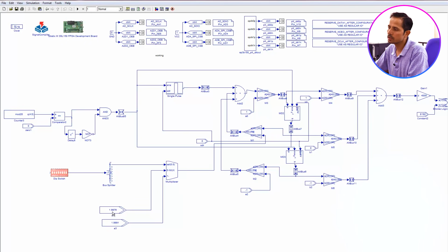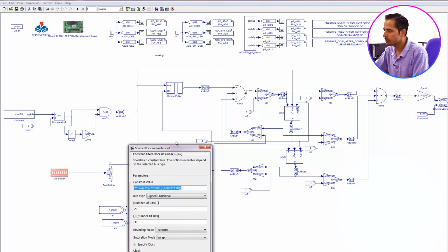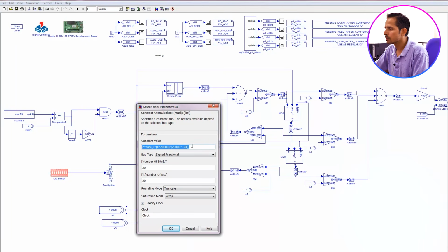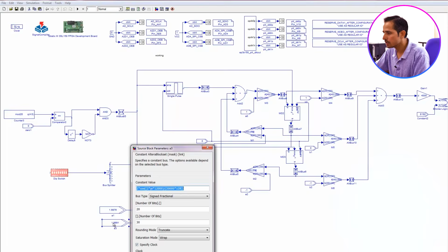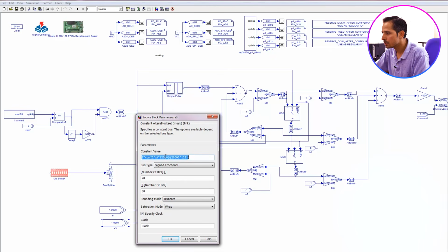So it should give me around 19.53. You can see here we have given the 2 cos theta value, and n is 128. So it should be able to give me 2 signals: 19.53, and another one which is approximately around 12 kilohertz. It will be giving me somewhat less than 12 kilohertz, because the sampling frequency doesn't match exactly, which is approximately 11.7 kilohertz.